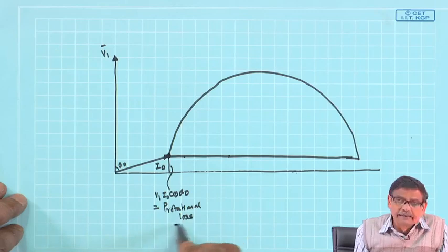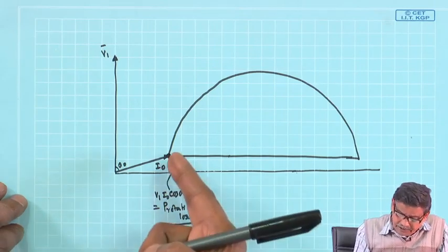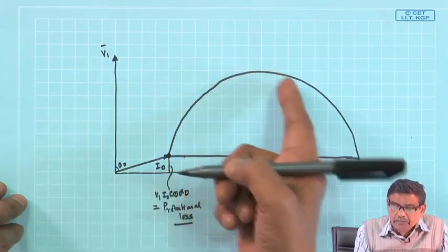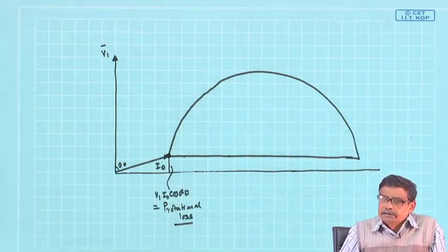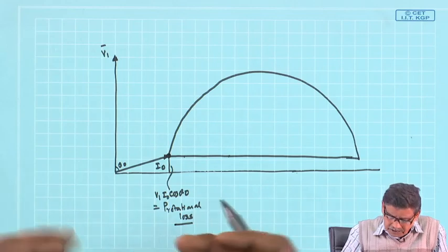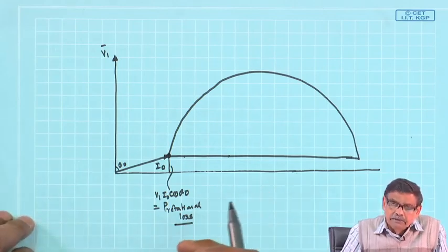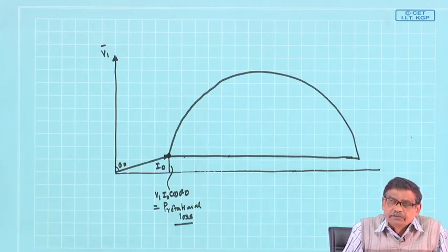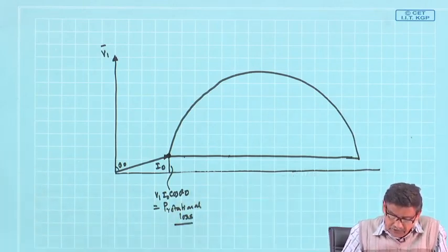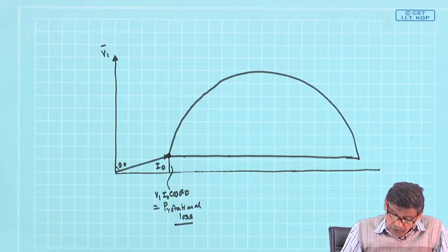And as I told you earlier, it does not depend upon at what slip the machine is operating, because the induction motor is practically a constant speed motor. Friction loss change we neglect, flux change we neglect, though a little bit of change of flux will take place. So, this is constant. Okay.